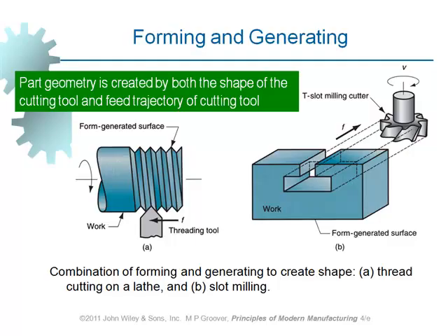Take a look at the geometry which is machined, then take a look at the cutter which is used to make it. It's somehow telling us about the shape and geometry of the cutter. However, it's not exactly the same. It is similar, right? For example, in that one, a T slot is made. But the cutter which is used to make it is rotational. The slot is not. However, the geometry of the cutter is left on the workpiece. So it is somehow telling us something about the shape and geometry of the cutter.